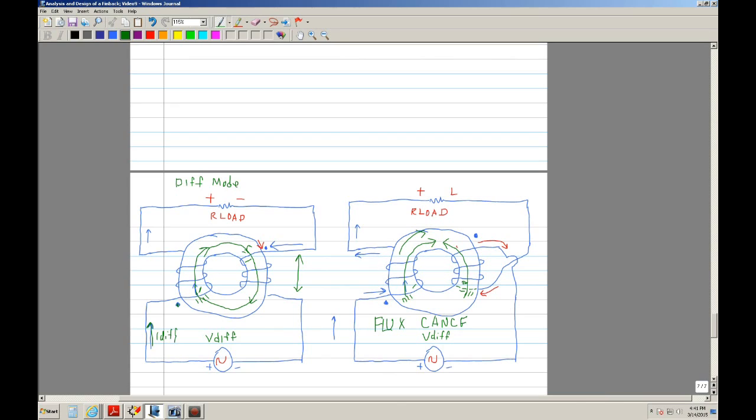That's very important. What does it mean? Well, if you don't have any flux, it means you don't have any inductance. So in this case, if you were to put a differential signal in here, instead of having attenuation or inductance through here, this is just a piece of wire. It has no inductance. It doesn't work. It would not filter any differential output.